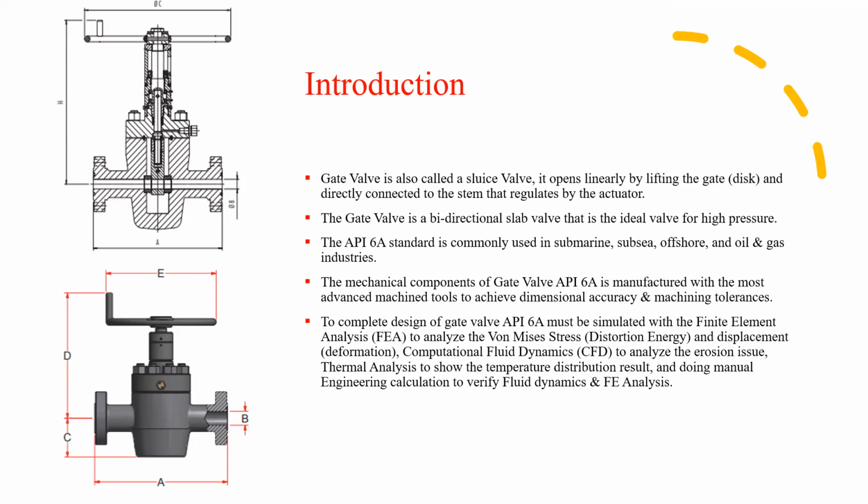So, in our project, to complete the design of a gate valve API 6A, it must be simulated with finite element analysis to analyze the volumetric stress, which is also called the distortion energy, as well as displacement or deformation. Also, we have done computational fluid dynamics, CFD, to analyze the erosion issue.